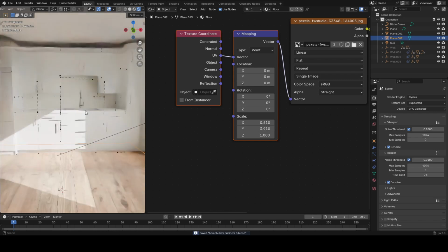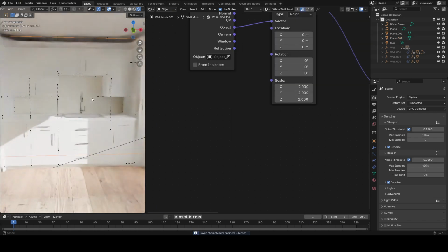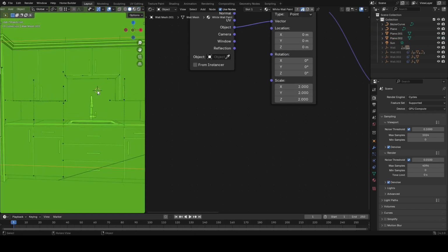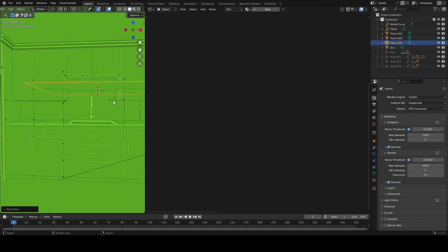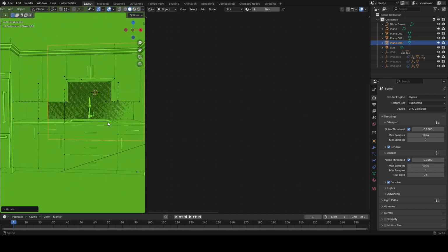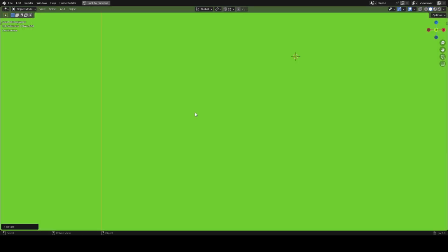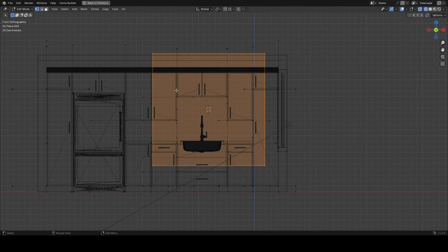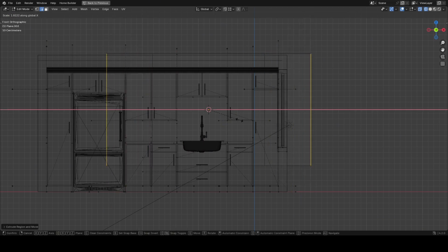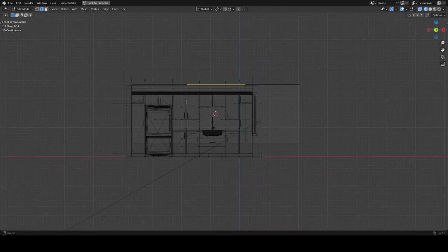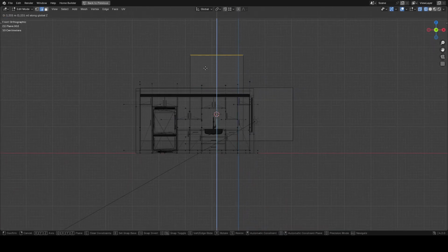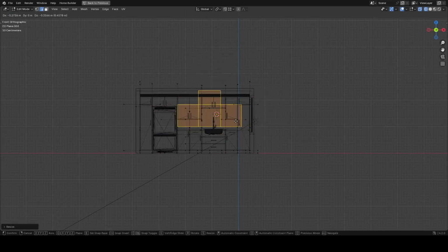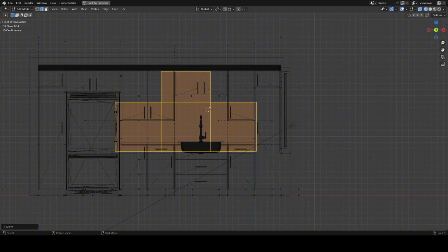Now, interesting. So now let's assign something in the background. For here, I like to add a plane, rotate it 90 degrees in the x-axis, and let's press Control Space. What we need to do is select these two, press E, and move those in the x-axis, and select this part, E for extrude in the z-axis. So now we move everything in this part.